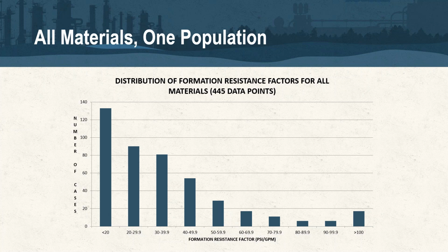And where I'm going with this is that when we do these types of injections, Derek hit it pretty hard and covered it pretty well, but I'm going to say it again: we're working with existing features and porosities within the formation itself. We're not creating new features. We're not trying to break the rock itself and inject into new material. We're utilizing existing pathways and flow paths that would be both your transport zone for groundwater and, more importantly, in contaminant remediation, the contaminant itself. So what we're trying to do is take advantage of that. That's why the upfront RDC work, looking at the geophysics and the pumping test data, helps us better target these zones where we can take advantage of those features that already exist within the formation. Next slide, please.